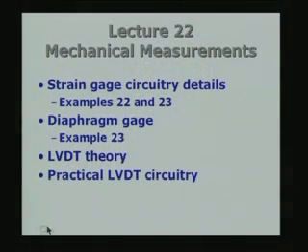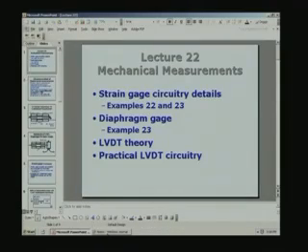So, in essence, the present lecture looks at the measurement of displacement and relates it to pressure, and by two different methods, one using the strain gauge, the second one using an LVDT as the transducer, which changes the pressure signal through a diaphragm or a bellows to a change in displacement or a movement, and then that is sensed by using the LVDT, which is essentially an electrical means of looking at the displacement. So, let us look at the method of measuring the strain.